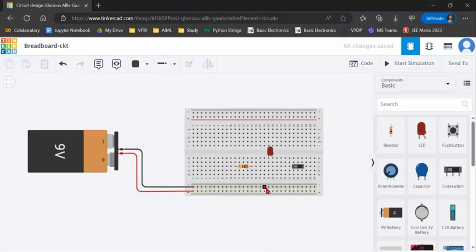So whenever you have connected something by mistake, you can press escape and it will be disconnected. Or if you want to remove anything, like suppose we have selected this button but we don't want it, we want to use the wires, we should press escape on the keyboard and it will be deleted basically.